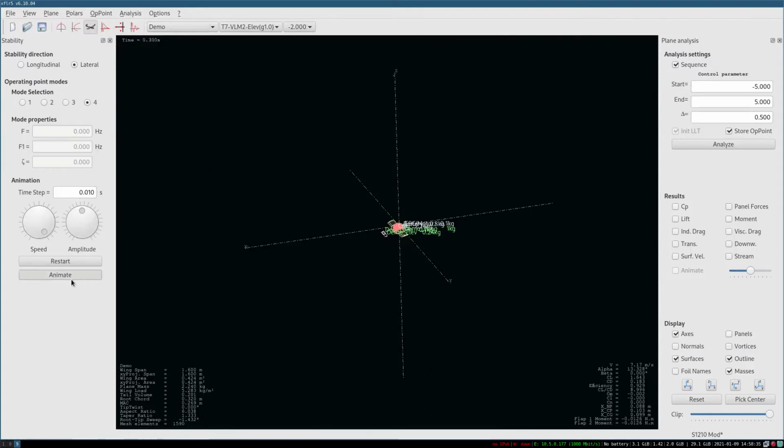Again, this is why these analyses are performed. This is looking a lot more like a spiral mode, where you have many seconds, and the aircraft does eventually fall off screen. That's fine. But again, you've got 4 or 5 seconds on your spiral mode to do something about it. Does it show me the exact